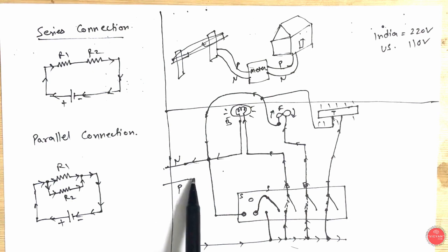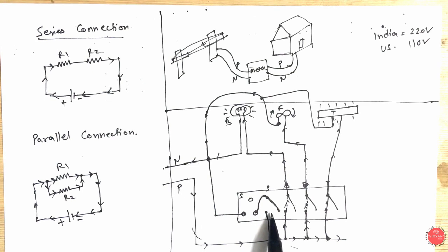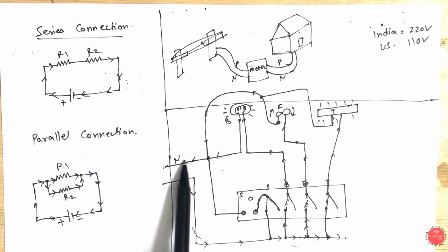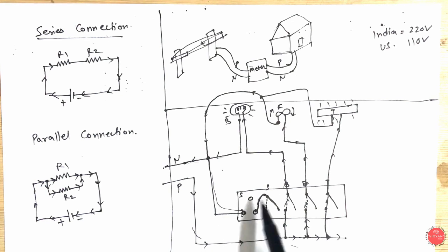So in this way, phase is flowing like this, like this, like this, and see that the key is open, so no current will flow further. Once someone switches it on, it provides the phase here, and a neutral is being provided here. So the circuit is not yet completed. Whenever you provide any charger or any extra bulb through a bulb holder, you need to put it to both ends, and it will now complete the circuit, and the charger or that bulb will start working.